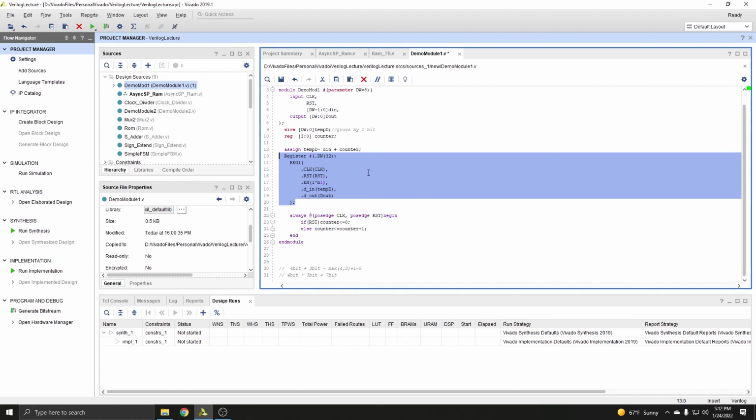Also, don't make a bunch of the same module, utilize parameters. In the past, I've seen people make basically 8 of the same register with different names, not knowing that they can make one general register and reuse it. So please save yourself the time, the work, the extra effort that you don't need to do, and reuse all the work that you already did.